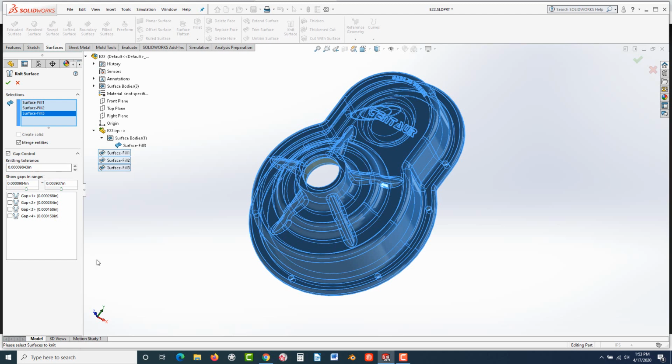So what you have with this one is, in earlier CAD systems, they used to work on a much lower level of accuracy or precision. This is a double precision modeler, more of what we call a modern modeler, versus back in the 70s and 80s, when computers were much weaker, they actually went with half that, or even some systems were integer based versus floating point, to just speed things up. And therefore you had very low tolerance precision when it would stitch multiple surfaces together or quilt them. In more modern times, you could put in much higher precision. But perhaps if you're working on an older model, or if you import a model that's from the 80s, you could loosen up or make it very low precision, and it'll look at it as a solid and actually still work. Let's hit the green check mark here.